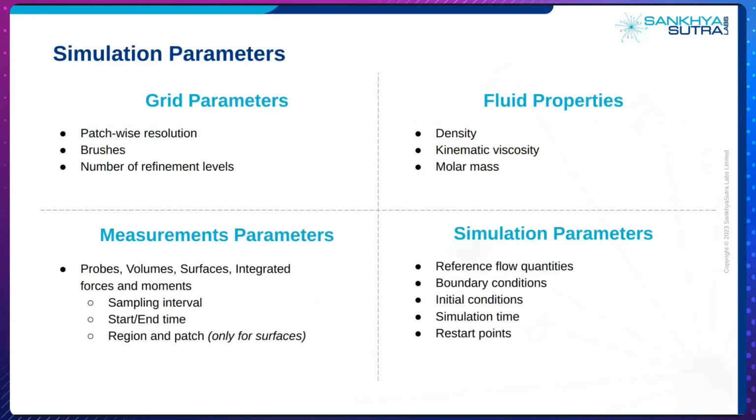For the simulation parameters, as I said, there are 4 categories. In the grid parameters, you can set your resolution. So you can always set patch-wise resolution. Patches are essentially certain regions in the STL that are demarcated by the user based on their specific interests, such as applying different boundary conditions on different surfaces, etc.